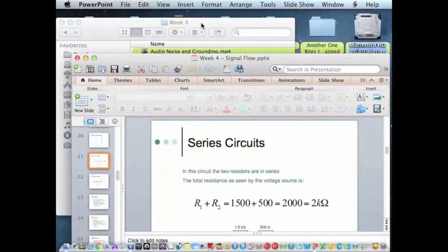This is all passive at the moment, meaning that there's no real amplifier involved. What I'm trying to show you is that with a capacitor and a resistor, you can actually manipulate sound, or the electrical signal that'll eventually become sound when it hits the speaker again. And that's actually what you do when you turn your knob on your guitar or your tone control on your stereo or whatever. You're actually manipulating those electrons to pass in different ways.